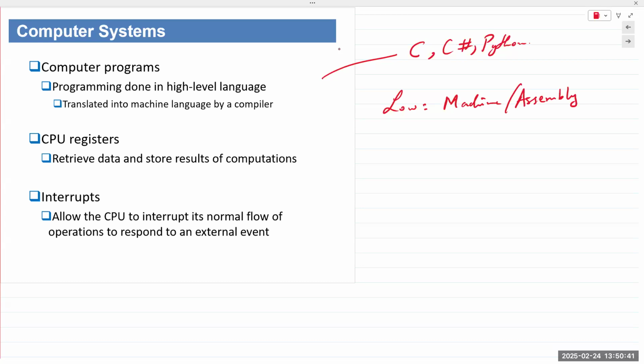And then how does the CPU know which system it needs to pay attention to? That is handled by something known as interrupts or polling. Polling is basically a CPU or a processor monitors the sensors that are connected to it in a sequence. It continuously monitors or polls the sensors. Is there any new data coming in? Is there something else that needs my attention? That's what polling is. Obviously, that's a waste of time if you have a complex computer system.